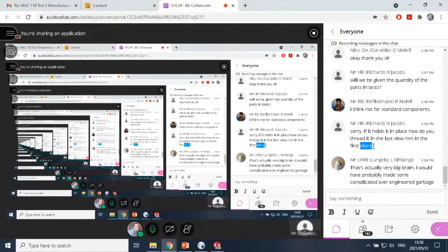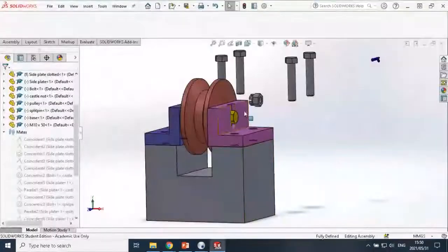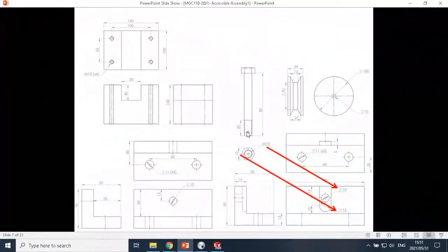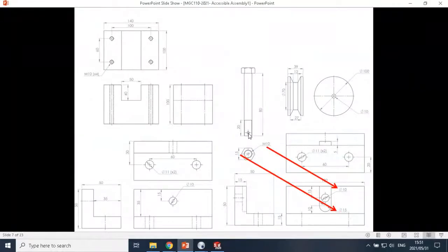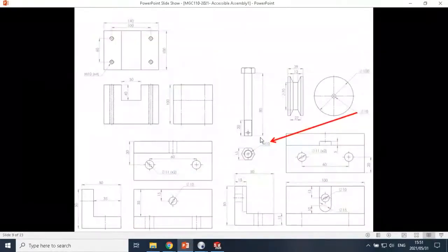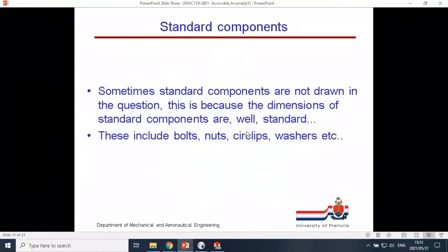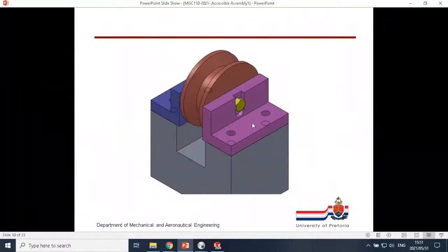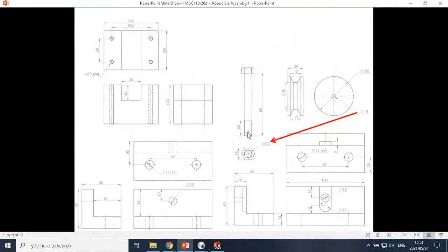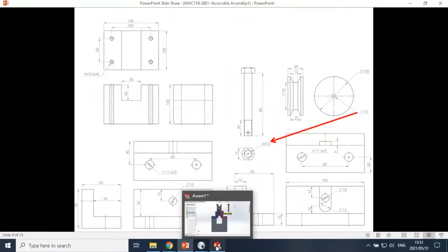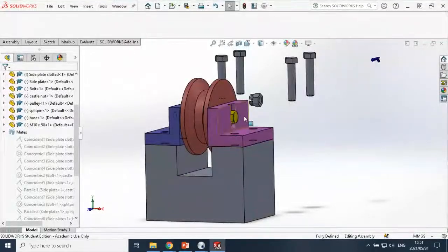You'll see what I do now. So basically, the bolt gets pushed in all the way by hand. And now we have a bolt with a little hole in the threaded part. Okay, so a bolt with a hole in the threaded part, like it is shown over there, usually hints towards a castle nut and split pin that is going to be used.